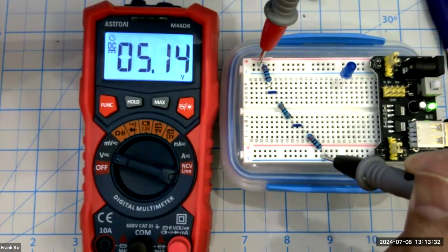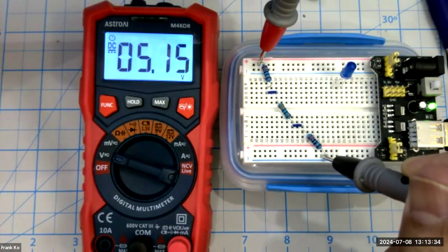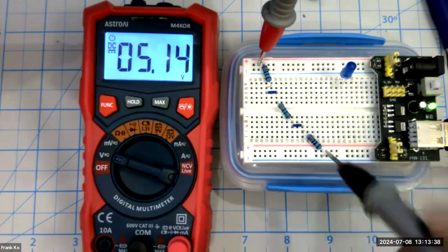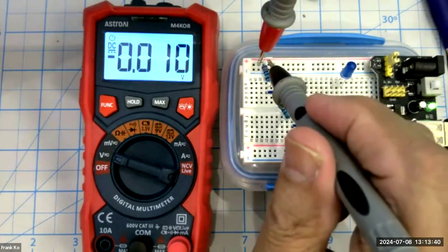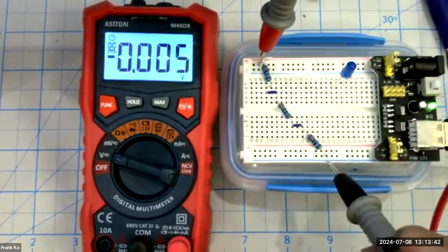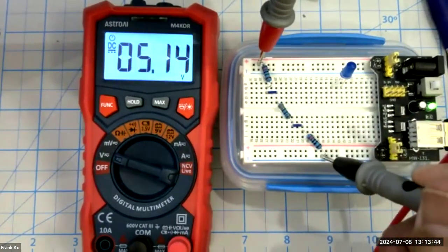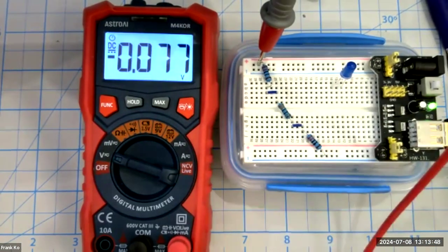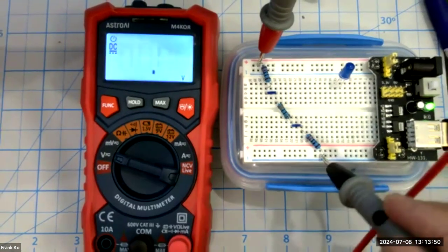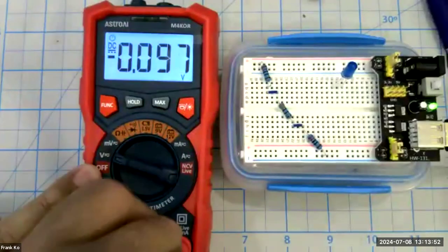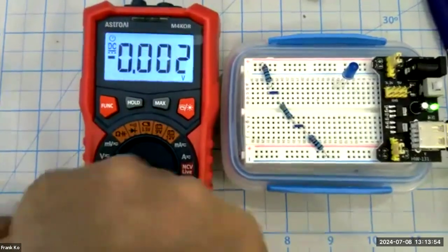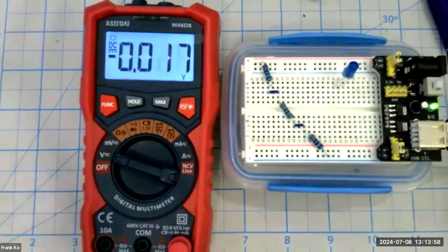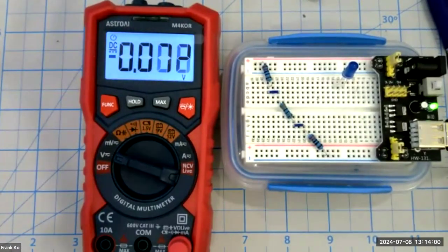Okay, all right. Now the voltages at specific points, voltmeter number 1, voltmeter number 2. Voltmeter number 1 was connected across the first resistor all the way down to ground, and it should be the same as voltmeter number 4, total voltage. For voltmeter number 2, I'm going to leave the ground here. In fact, what I'm going to do is what we typically do in the field, and that is we leave a permanent connection to ground.